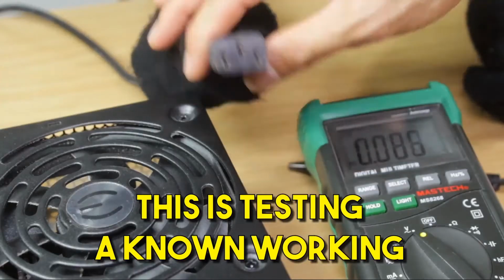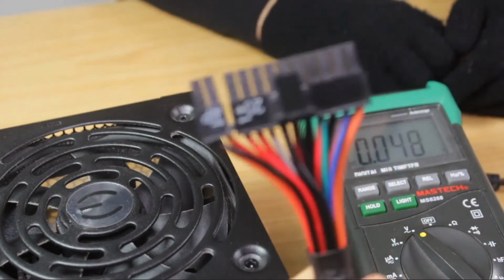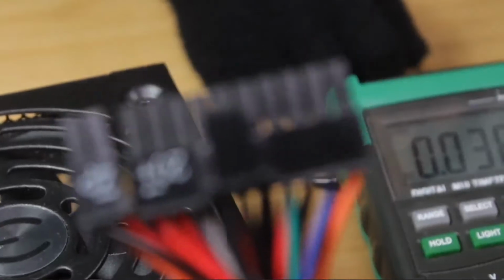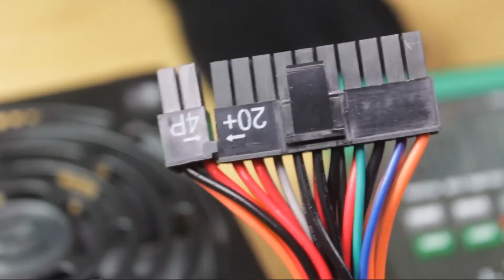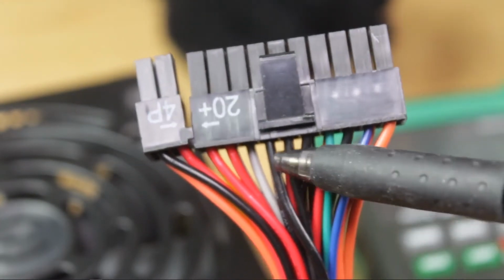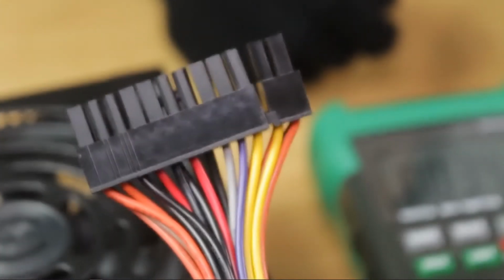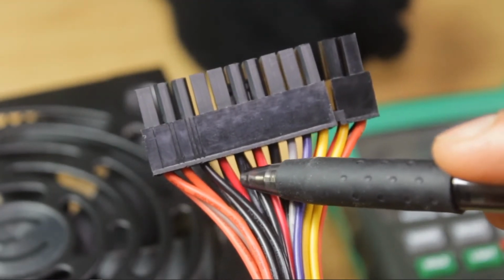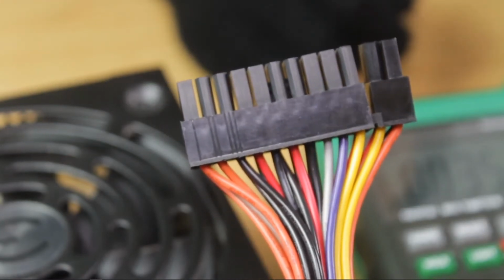Next thing, we're going to put that on the side and take our power supply, which is currently still disconnected and unplugged. On the power supply you're going to see there are 24 pins, and they are color coded. There are some power supplies which will have only 20 pins. There are blue, orange, green, black, a gray, some more reds and black, and on the other side there is yellow, orange, a purple, gray, black, red, another black, red, black, and orange to finish off with.